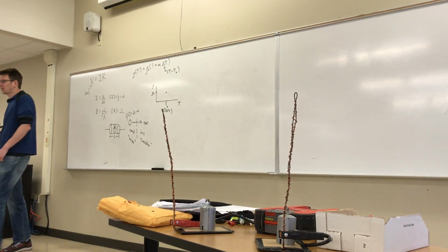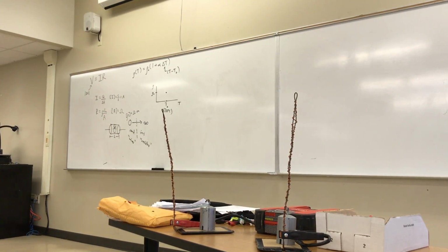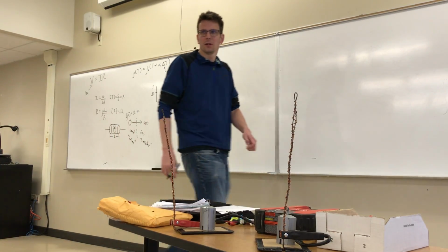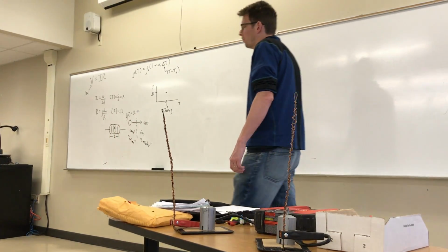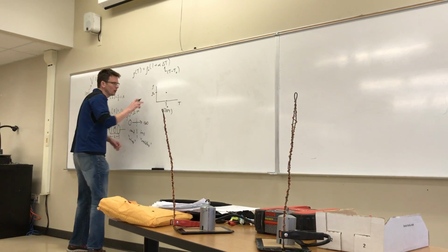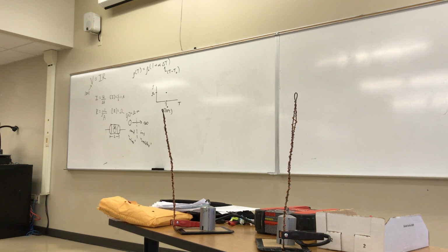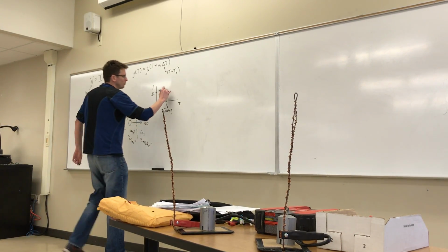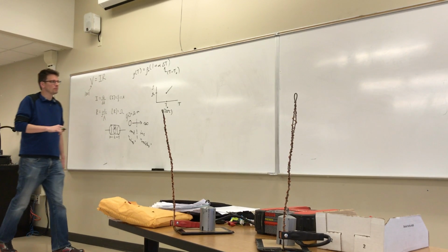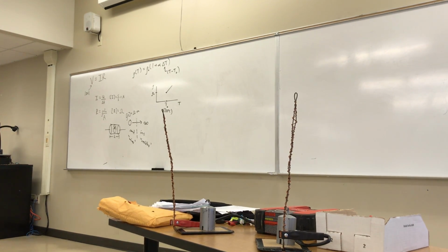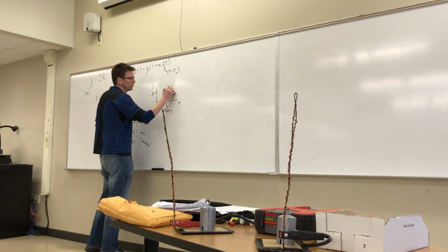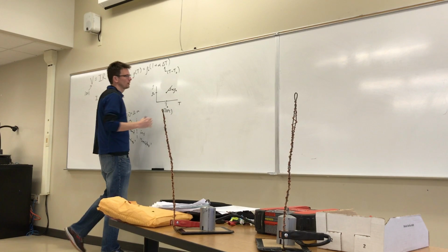And for instance, you can find on the equation sheet, it's on the third page in the lower left, lower right corner, you can find a table of what is the quote-unquote standard resistivity at that reference temperature. So that's your starting point. That's your baseline. But then, if you do change the temperature, you will change the resistance. So for instance, maybe it looks something like this. Now you can actually put this thing into point slope form, and you will find that the slope here is alpha times rho naught.